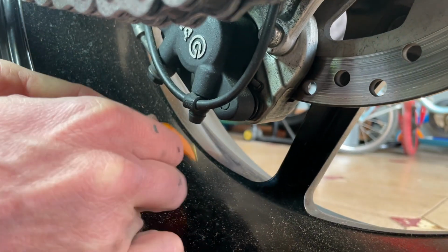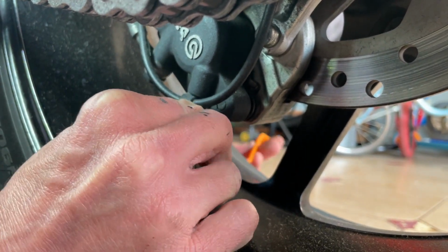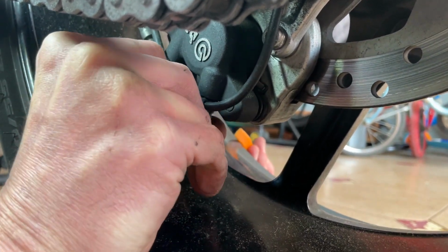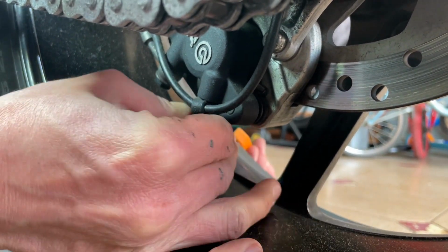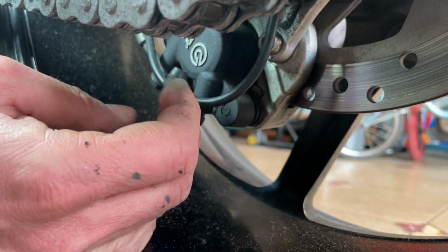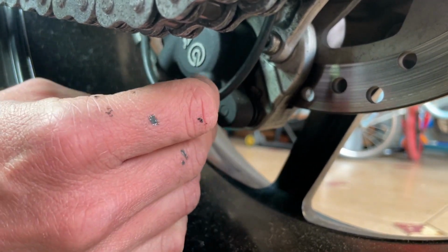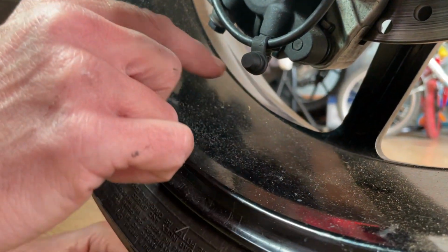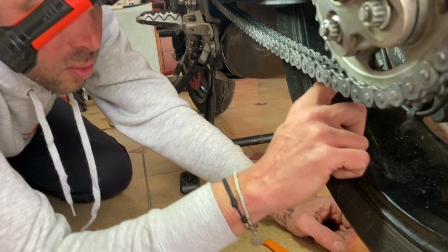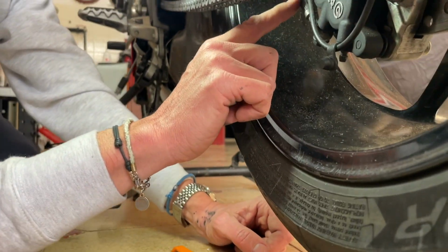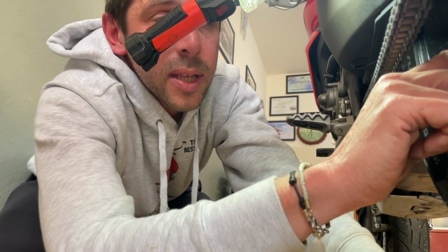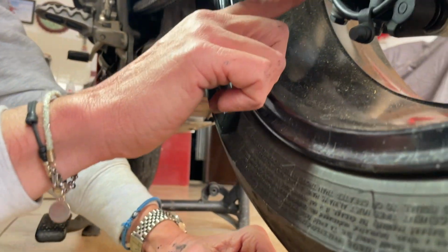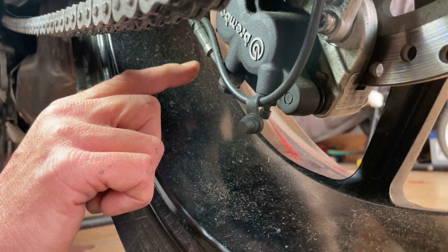So this bike is equipped with ABS, and this will mean also that we are going to have a bit longer way from the pump. Here we are, from the pump to this bleeding valve, because we have this pipe that does not go straight forward to the brake pump like all the bikes without the ABS, but is going to the ABS module, and then from the ABS module to the pump.